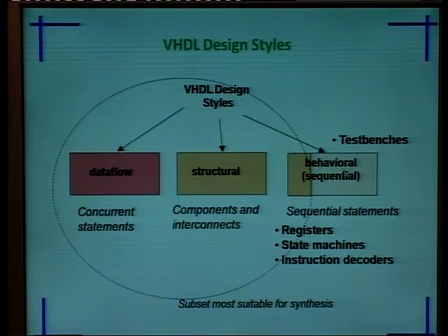But the main limitation of the truth table is that if we have to design an 8-bit adder, the number of input combinations will be very large. If we have to design a 32-bit or 64-bit adder, then you can imagine the huge size of the truth table. So, to minimize that problem, we have to go for the structural style. In structural, we write components for small separate modules and combine them together with interconnects, and then we simulate, and the code length is very small in structural.